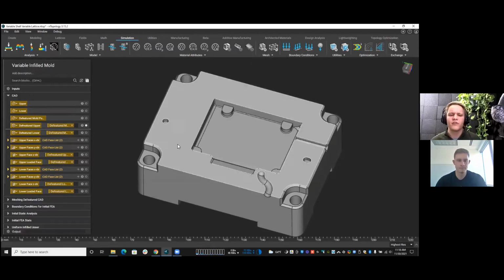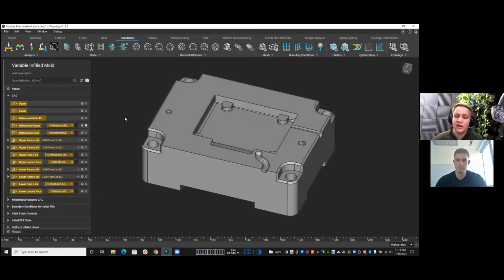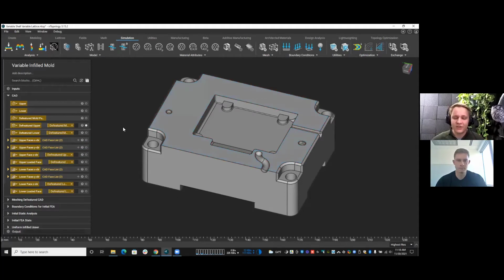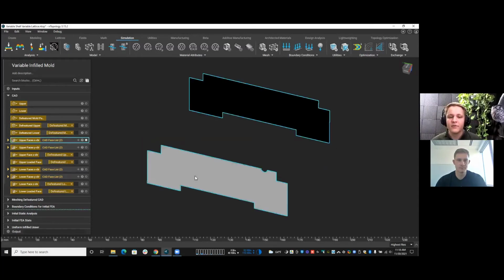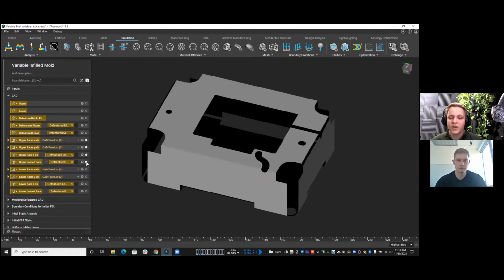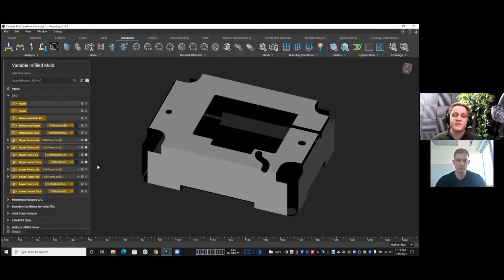Nothing special or fancy. For the remainder of this presentation in nTopology, I'm going to focus on what I call the upper, because I'm actually looking at this upside down. We're going to focus just on this body here, because everything I do to this body, I also do to the other body. It'd be a bit redundant to show you both. I'm also going to make a few selections. I'm going to grab these two faces here, these two, the bottom, and the top. I'm grabbing all of these faces with just a couple selections in nTop, specifically for that FEA that I've been talking about, right?